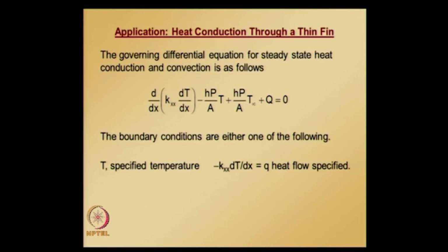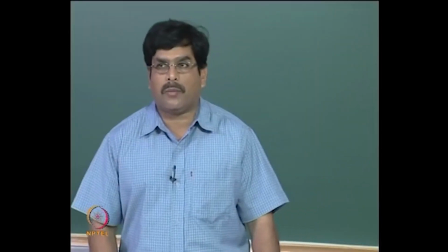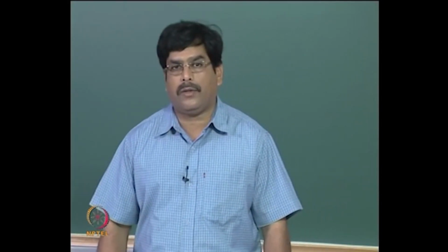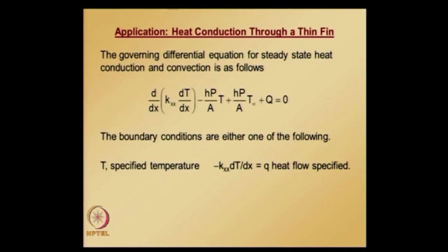And to develop the element equations, if you recall, we compared this differential equation corresponding to steady state heat conduction and convection with the general one dimensional boundary value problem, and identified the corresponding coefficients. Once we identify the coefficients, we already have element equations for the general one dimensional boundary value problem. We can substitute the corresponding coefficients in those element equations to get element equations for this particular case of steady state heat conduction and convection.